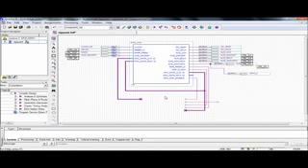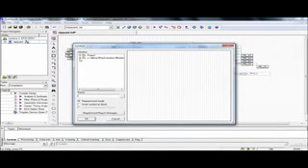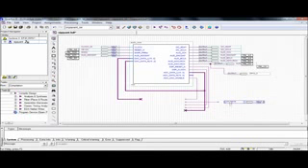After exporting the Simulink design into HDL block, open the Quartus II project file and insert the HDL block into the schematic. Click Symbol Tool icon and then select the input symbol from the pin libraries. Double-click the pin name label to rename the symbol as SW1. The label SW1 is assigned to the switch labeled SW1 on the DE2 board.